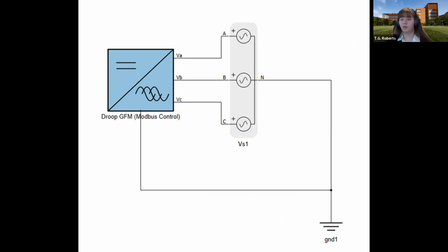The grid forming inverter, power stage, the filter, the inner current and outer voltage loops, as well as droop control are all emulated in the 604. So essentially everything you see here except the synchronizer is implemented in the HIL 604s, and the synchronizer itself is implemented in the target hardware on the 404s.